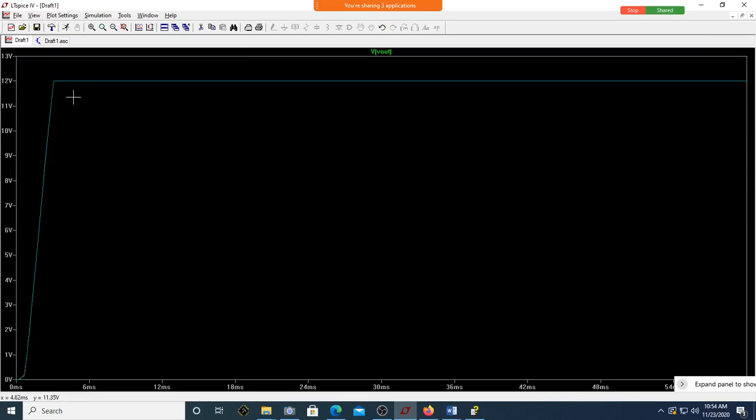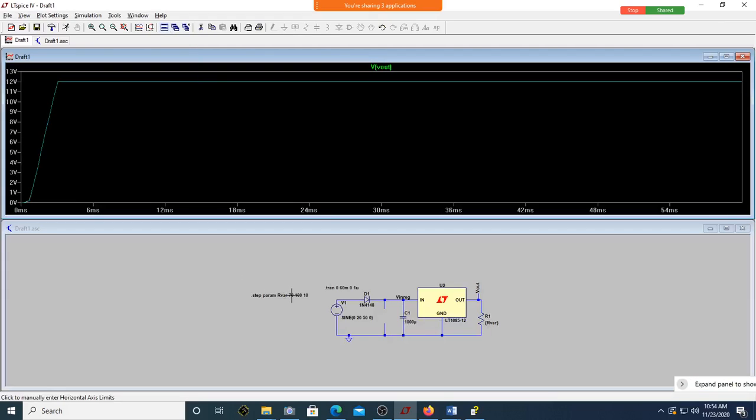can you see it's almost there? They are actually overlapping. So even if the resistance is 70 ohm, 80 ohm, 100 ohm, this is actually changing from 70, 80, 90, 100. Correct? For all the resistances, even though you are drawing more and more current, the output voltage is fairly constant. Is the output voltage constant here? Yes, sir. Even if I increase the resistance, for 70 ohm it is the same, for 80 also the same, for 90 and 100.